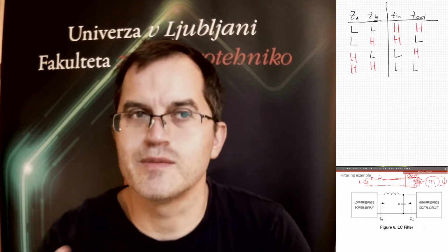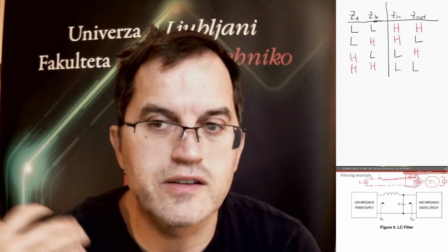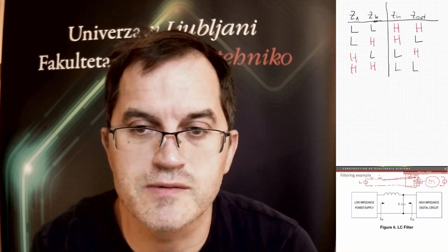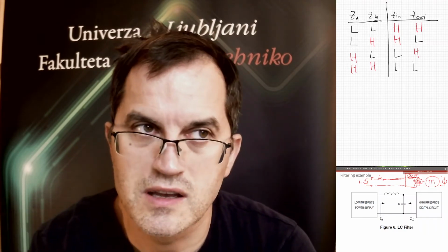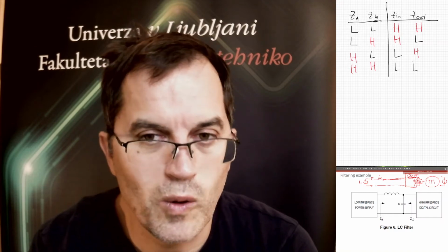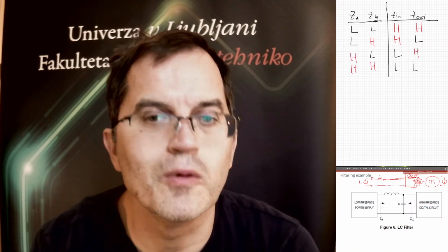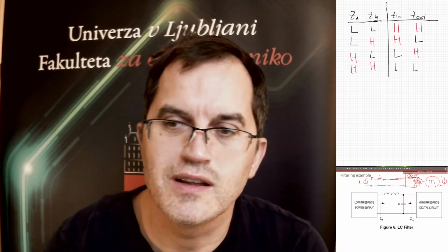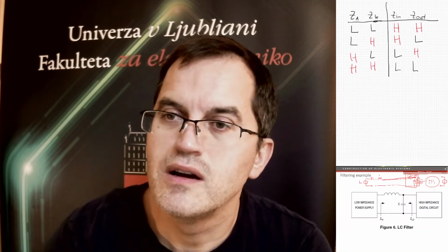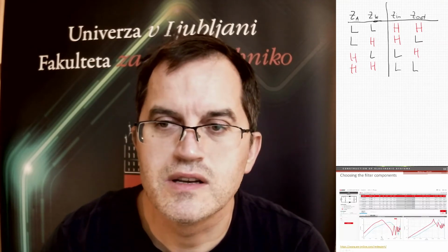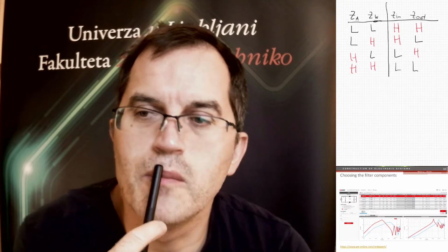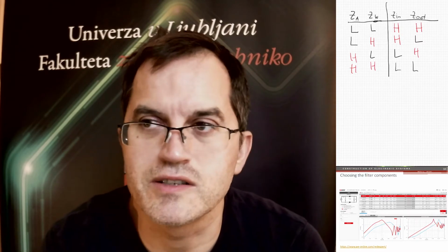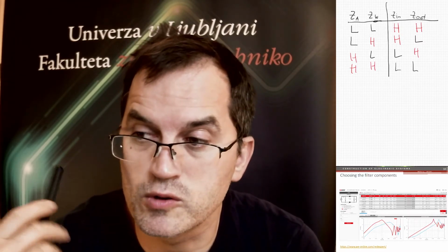Therefore, you have to use some simulations. And there are some tools you can use, like SPICE, for example. But nevertheless, if you use SPICE for simulating the insertion loss, you still have to know how to model all the parasitics and how to model the impedances of your circuit. Therefore, for example, you can also use a kind of component, I would say, online calculator, like for example REDEXPERT from Würth Elektronik.